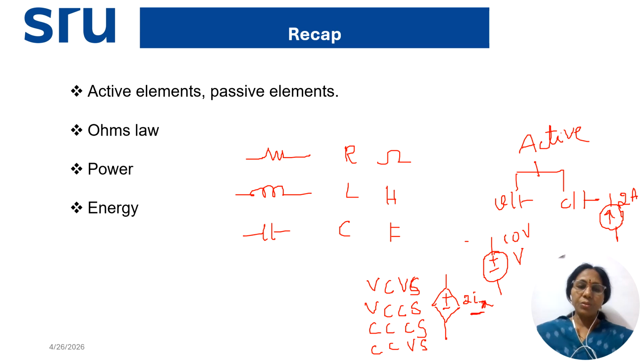So the magnitude of this voltage source depends on another branch current. Like this, if I write here 2 Vx or Va, Vb, multiplied with some number, where this parameter is a voltage at a particular branch in a network, it means the magnitude of this voltage source depends on another branch voltage. So this is about the dependent voltage source.